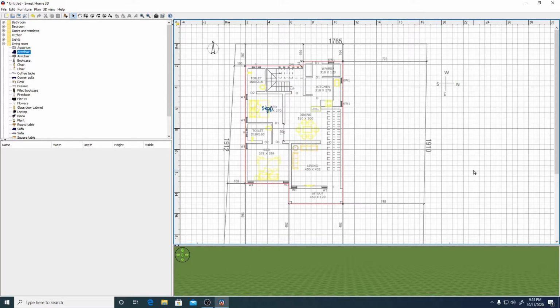Okay, so before that, one more thing you have to note here is, my north faces this direction, but as per software it is this direction. So let's make it in sync so that everything is correct. Why we are doing this is, when you do the lighting of the buildings you will really understand the difference. But make sure that your north on the background image and here matches. Now let's start drawing the floor plan.